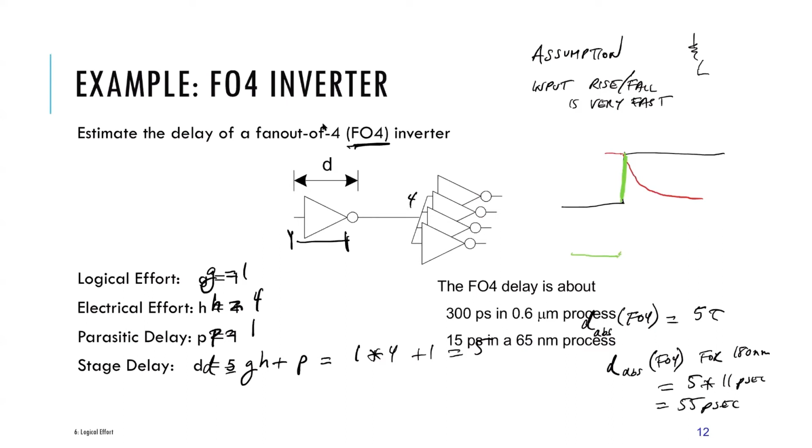Then your rise time will have some slope, and that will affect the transition of the next stage. In my opinion, this is the biggest difference between this and what you'll see in simulations, this effect of the rise time. And I think we'll get a chance to talk about how we can make up for that.